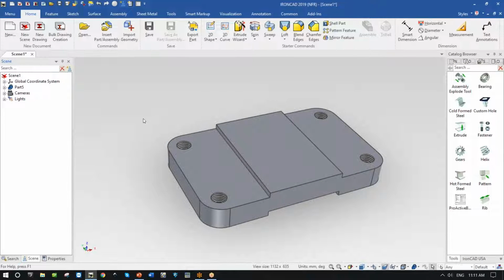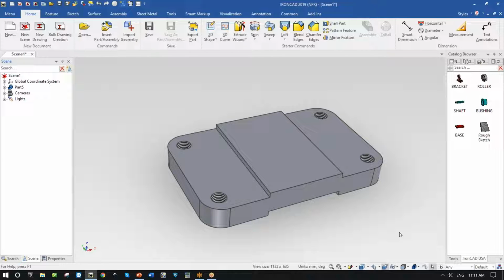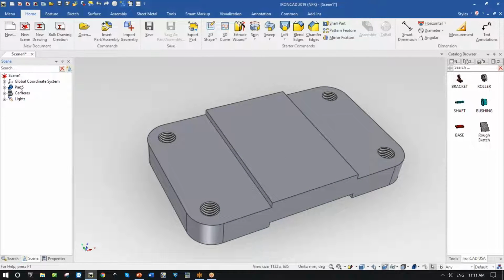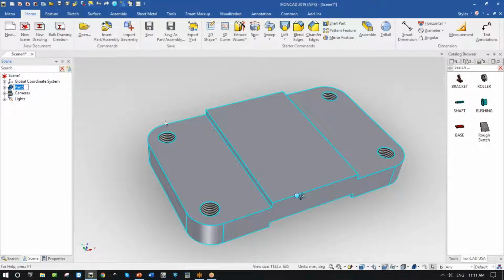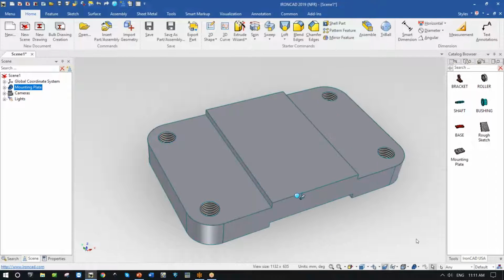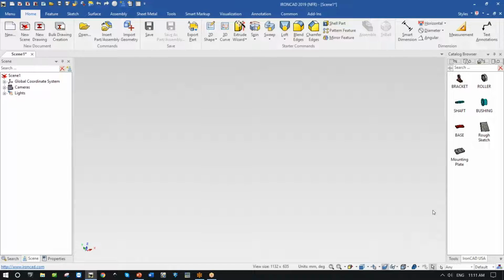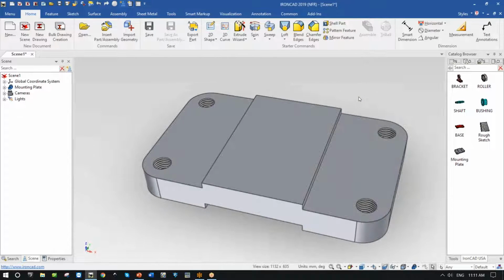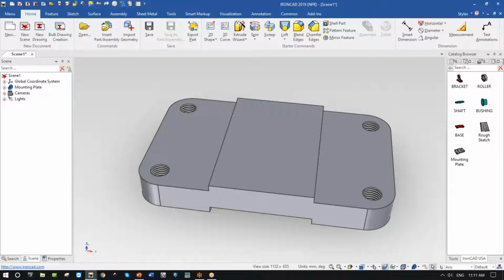And I've now created the first shape in this assembly. And that's an exciting thing that we're going to be doing. And you know what? I'm going to name this, this is my mounting plate. And this is how difficult or easy it is. I just come over and say, this part is now my mounting plate, and I'm going to use this mounting plate again in the future. So what do I do? Simply highlight it, pick it up, and drop it into a catalog. And this mounting plate, by the way, is anytime I start fresh and come into my system, I can simply pick it up and drag it out. And there's the mounting plate ready for use anytime in the future with all of the information intact.